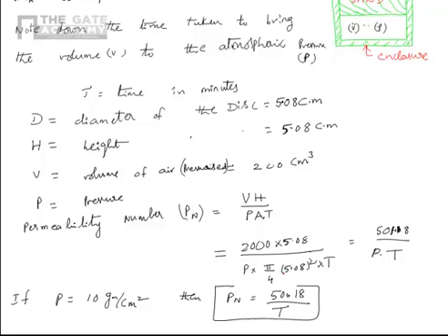So porosity is a property of molding sand. Permeability is a measure of quantity of porosity. So permeability number tells us how much is the porosity. If the time taken is more, it is less porous, inversely proportional. This is one of the important metrics, porosity.